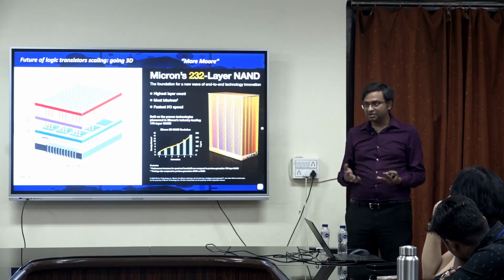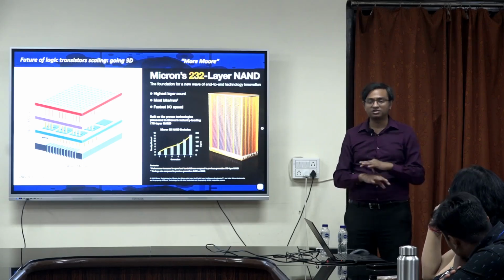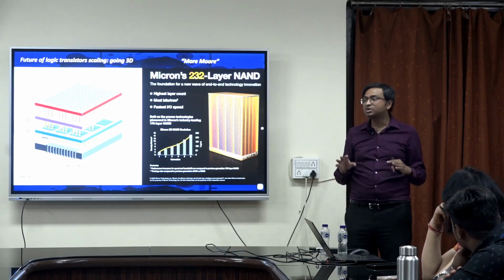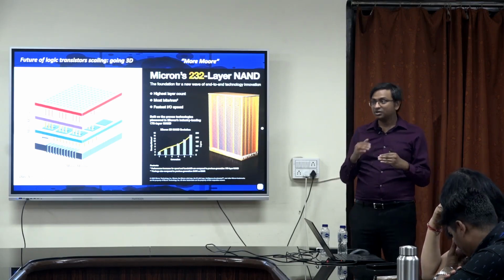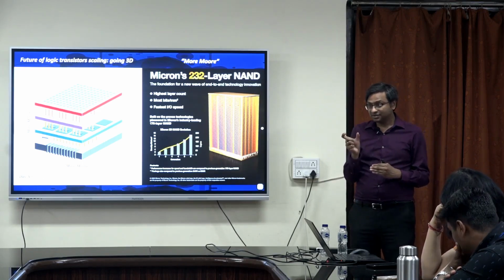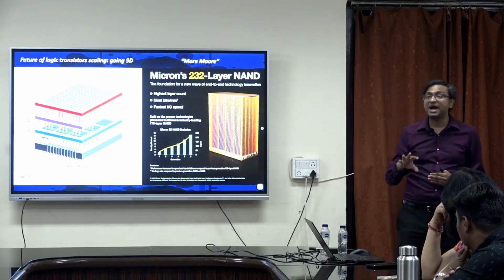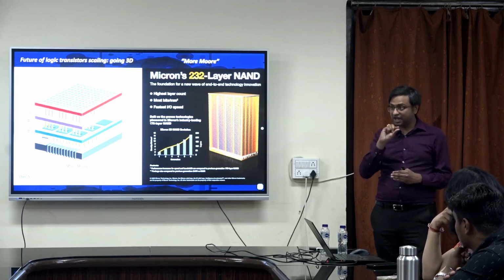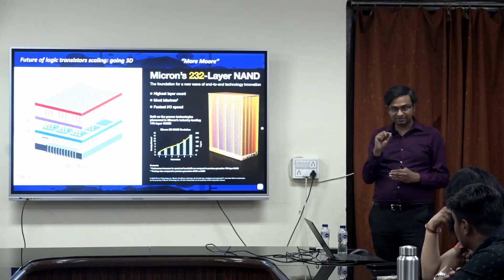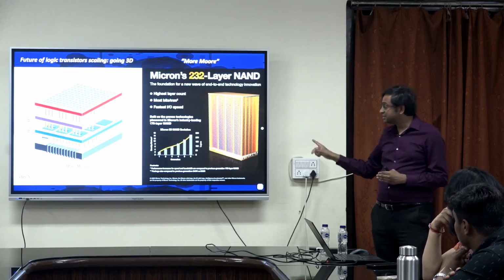And if you do that, then all your metal contacts, metal will start diffusing into your dielectric and all sorts of bad things happen. That is why you cannot raise the temperature of your chip, for high end devices, above 400 degrees centigrade. So, that is called the back end of the line temperature, which restricts putting high performance silicon devices on top of silicon devices. This is not true for memory.